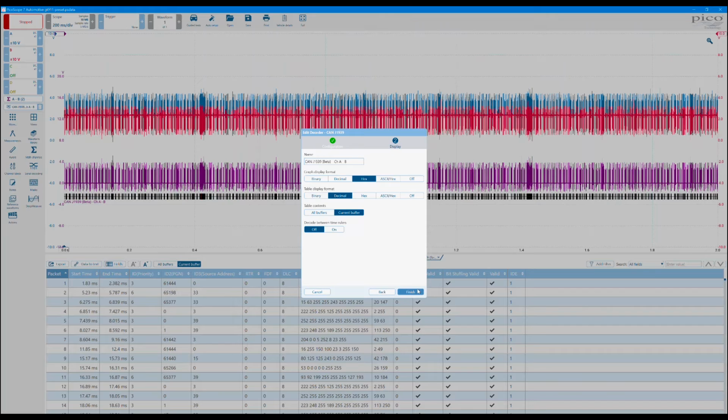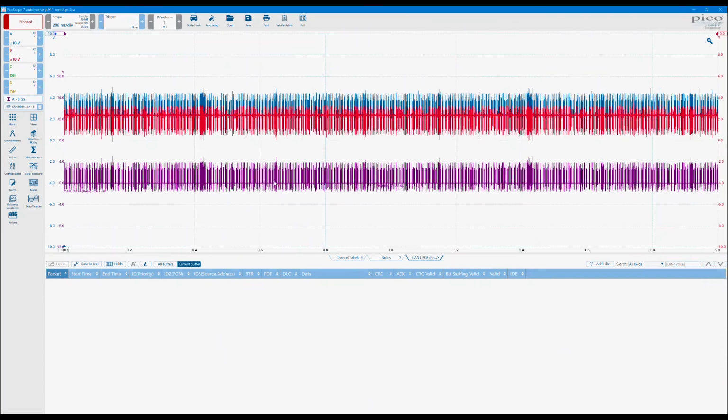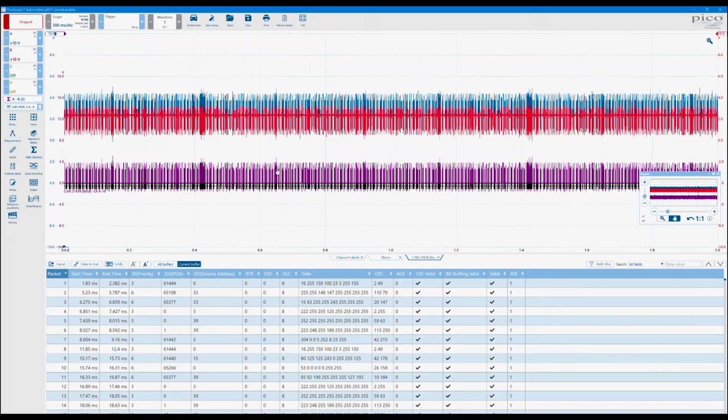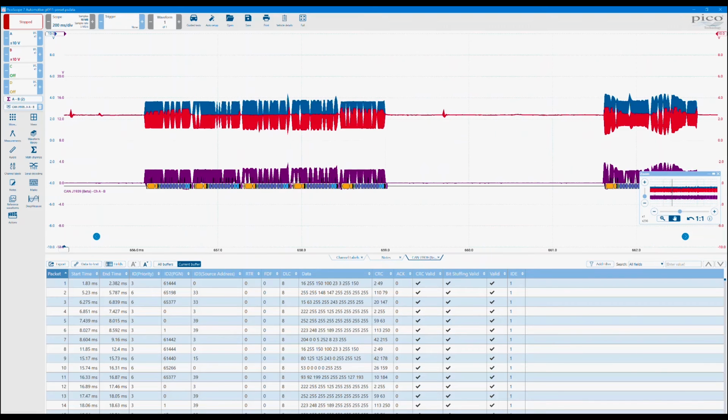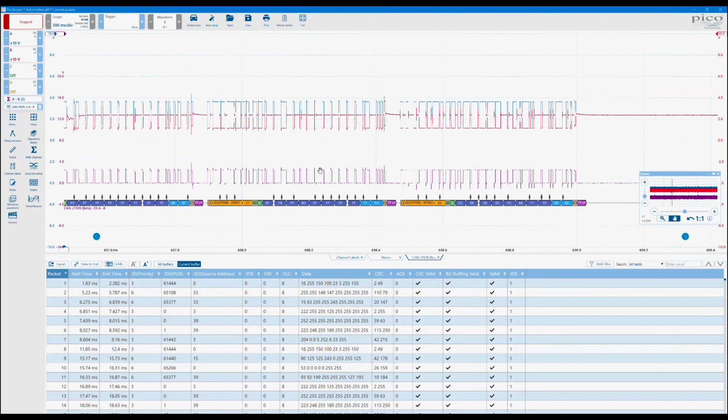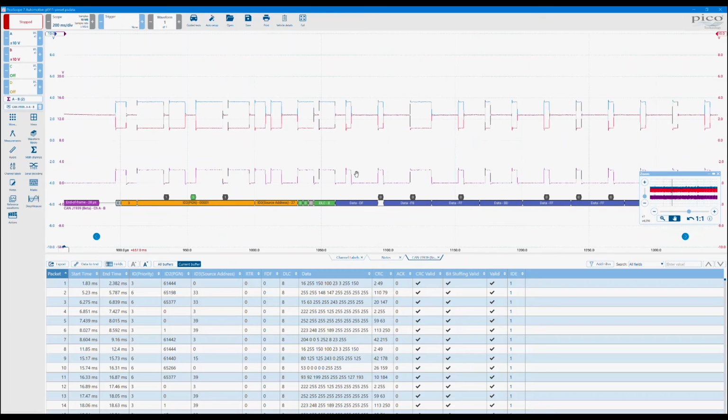A real quick, easy way to check what your baud rate is: if you go into a packet, so let's take this example here, all we're going to do is take 2 time rulers and measure one of the smallest pulses. This can be in any direction, it doesn't matter, so just literally the smallest gap.